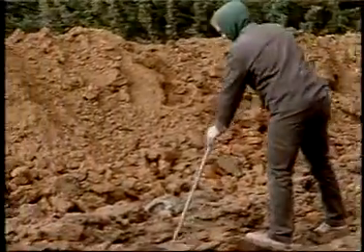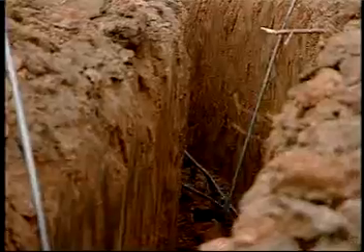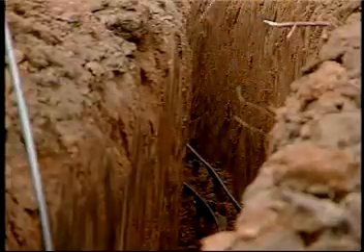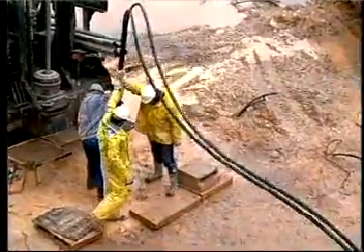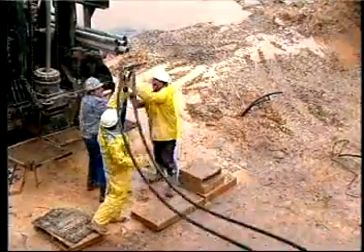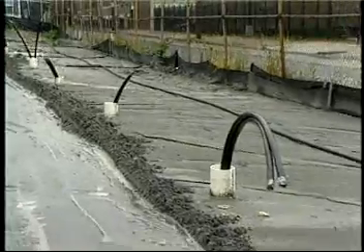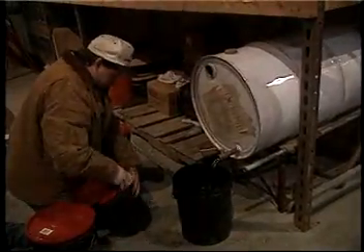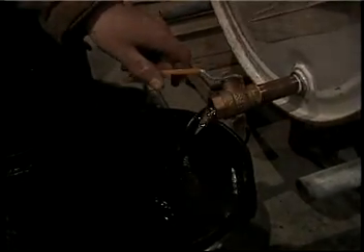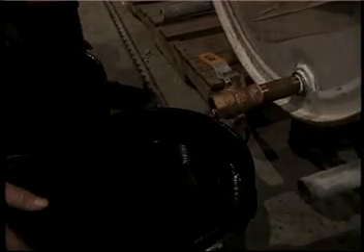The 2 types of heat exchangers commonly used are open loop and closed loop. A closed loop system uses a system of continuous underground pipe loops in which both ends of the pipe system are connected to the heat pump, thereby forming a sealed closed loop. Water, or a mixture of water and environmentally friendly antifreeze, circulates through the loop to transfer heat between the heat pump and the earth.